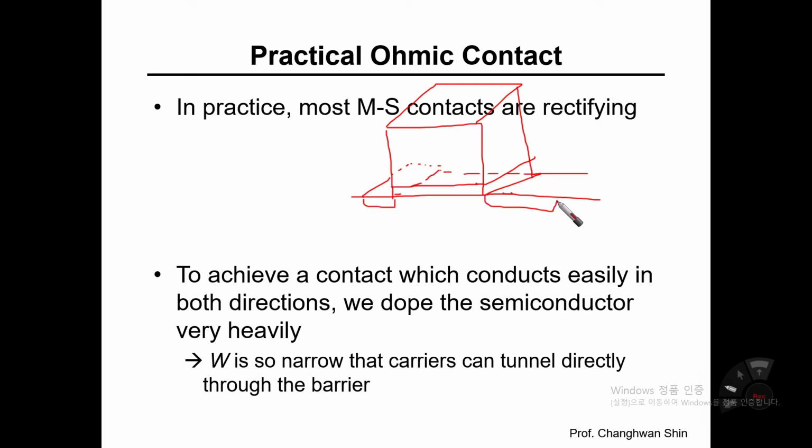This is a very simple MOSFET in a P-type substrate. So this is N plus source and drain, and that is the gate oxide layer and gate poly. Usually polysilicon has been widely used, at least in the 45 nanometer technology node and beyond.